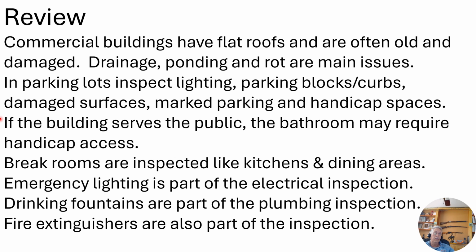Restrooms: if the building serves the public, you may have to have a handicap accessible bathroom. Break rooms are inspected much like kitchens and dining areas. They have fire extinguishers though. Emergency lighting is part of the electrical inspection, so make sure you check that emergency lighting.